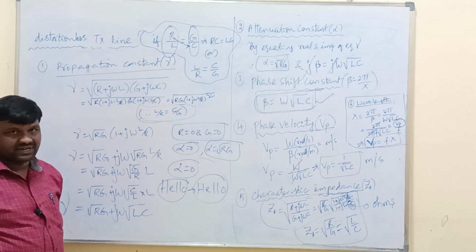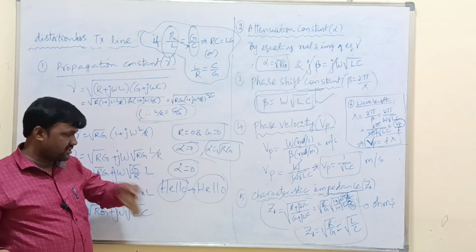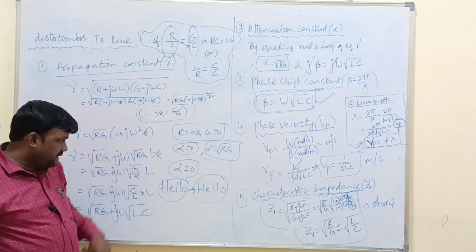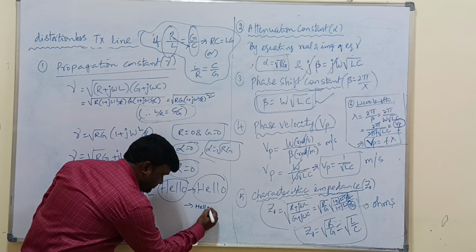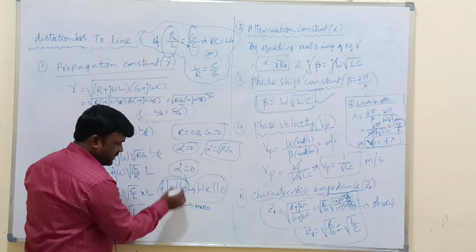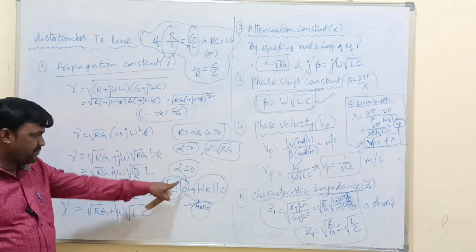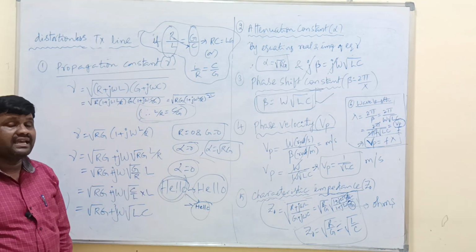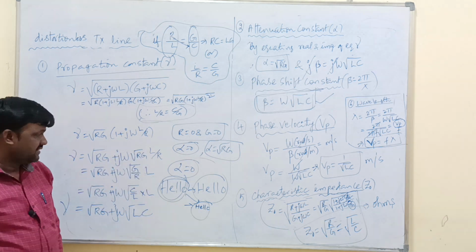Then the transmission is known as lossless transmission, or else without attenuation transmission. Suppose with attenuation, the strength is reduced like this. So this one is input and this one is output. Strength is somewhat reduced. Amplitude is reduced because of the attenuation. Attenuation means reduction of the signal strength over a distance.